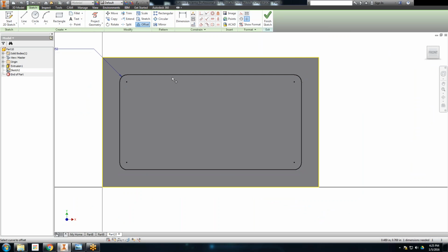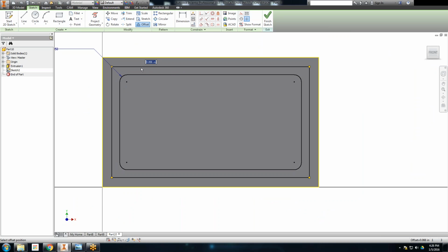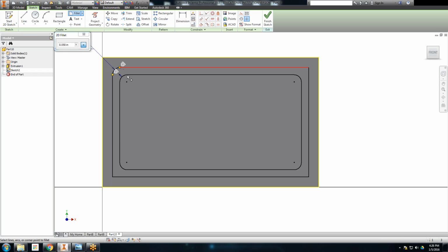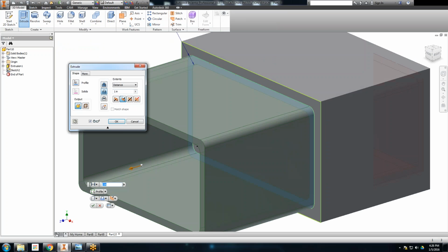So whoever designed the flange, if they had originally designed it like this, that type of thing would have been fine. It sees that as a slot. That's an even path. A slot basically wants to compare the two outside walls and then wants the tool to follow the middle of those two walls. Well, if those corners are like they designed it, more like this, these fillets are identical. If this is 0.05, then this one's 0.05, and HSM doesn't truly understand that as a slot because it's not. There's not an even path between those two, but regardless, this will still work for our example. We'll cut that.